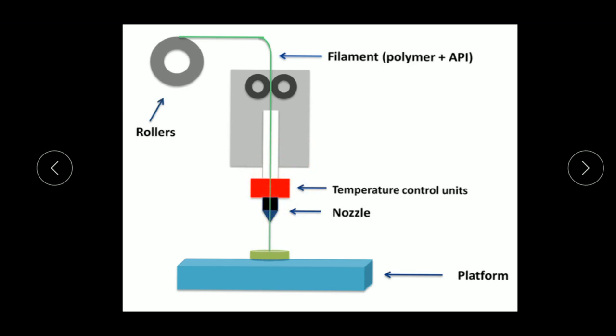The nozzle throat is set depending upon the thickness which you want, or which the customer requires. Now the temperature-controlled fused fibers come out of the nozzle and are deposited over the substrate. This process is continuous, which means the fiber is continuously fed into the temperature control unit and then comes out of the nozzle until the 3D object is built at the bottom. Hope you understand how it works. It is a very simple technique which is most commonly used in the Toyota company.